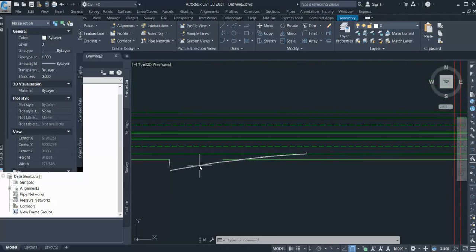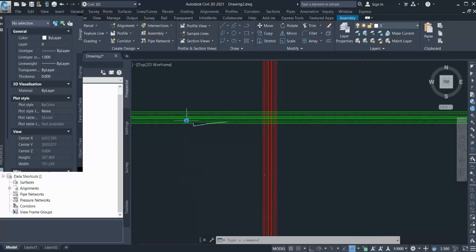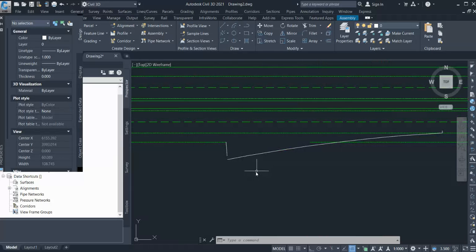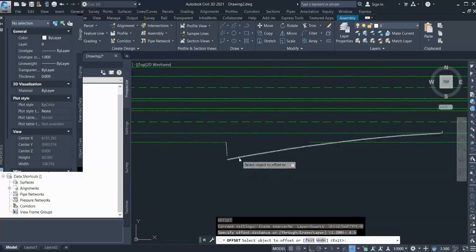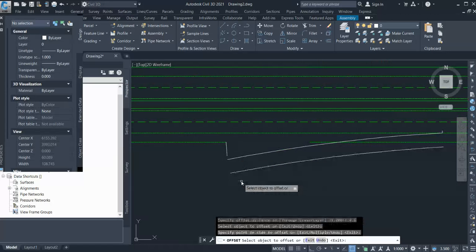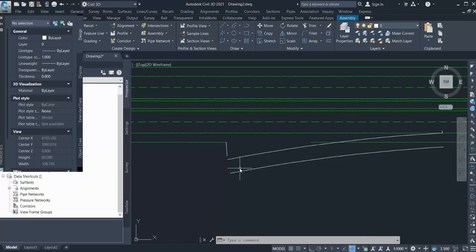Now your loop section is also a bit wide because you are providing some tight radius. So you should have a wide lane. If you are providing a single lane, it should be around 4.5, 4.6 something. And this is just taking one of the standards. You also need to check again your standard, what would be the lane width for the single carriageway or for the dual carriageway, what would be the width for your hard shoulder, left side or right side, or earthen shoulder. So my left side is 1.2, my right side is 2 meter.